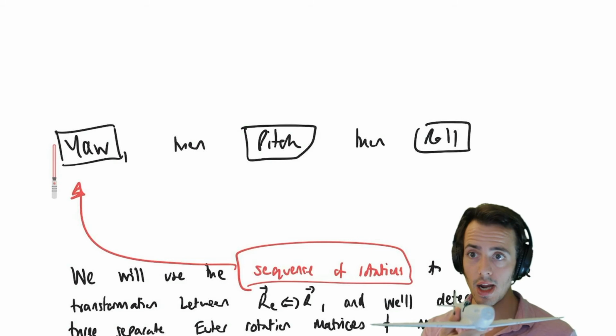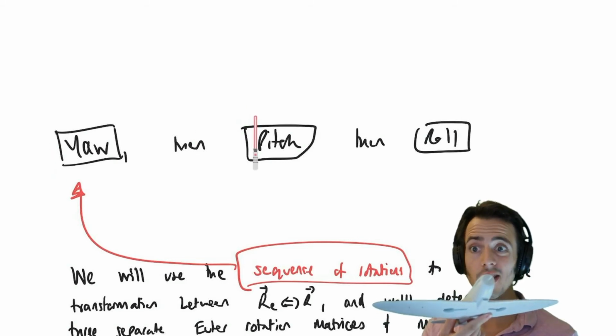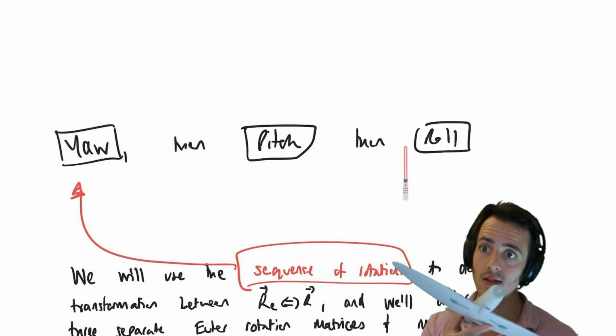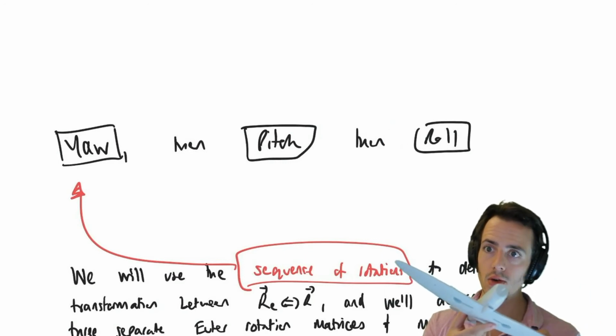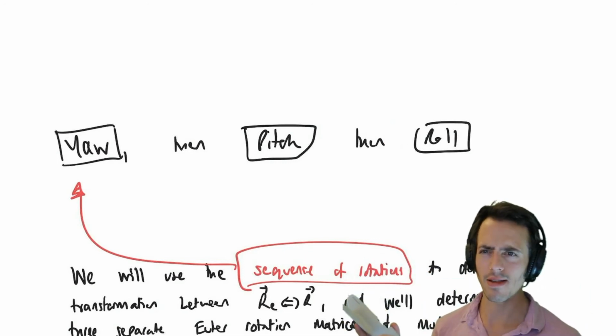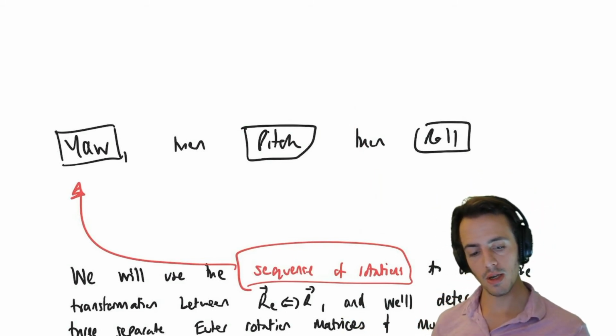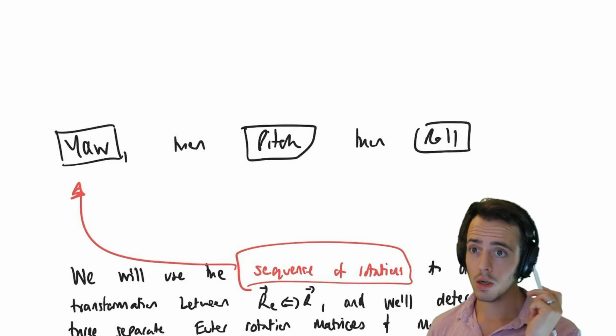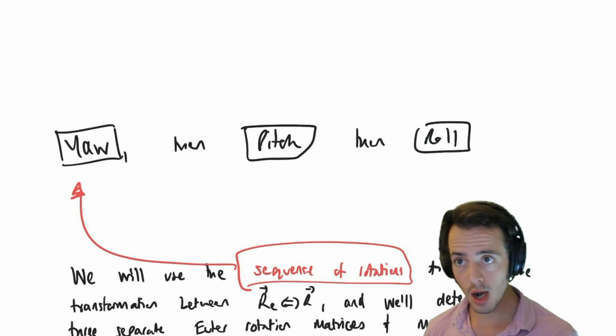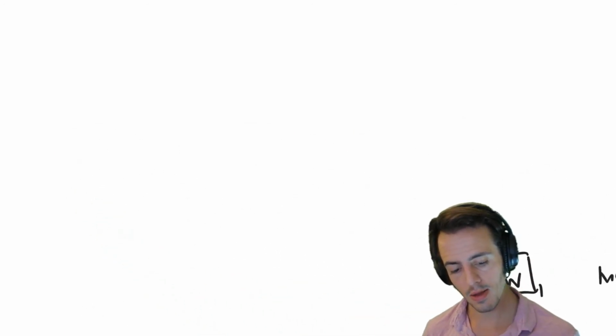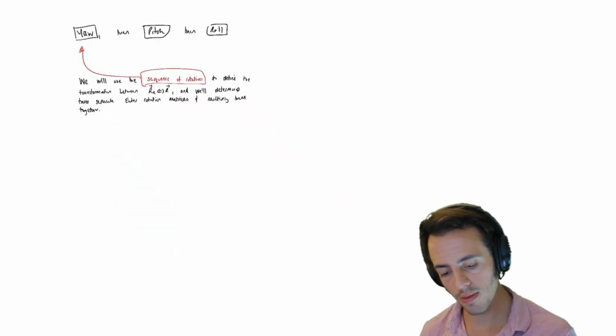Pitch then defines a relationship between that intermediate axis set and another intermediate axis set, and then roll defines that other intermediate axis set to body axes. So we're going to go through and develop these, and I'm going to go through the yaw Euler matrix first, and you guys are going to be left to look at how to do it for the other directions.